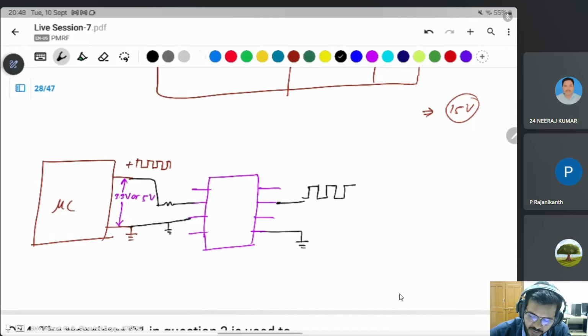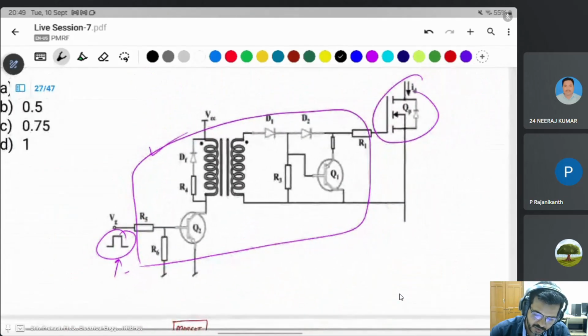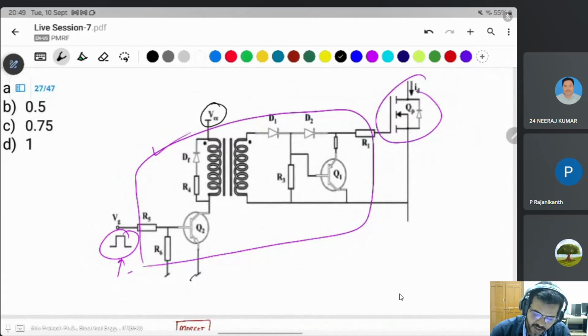Last, there is a requirement of a voltage supply. Whatever voltage supply you give to the driver is the same voltage given to the gate signal output of the pulses. This is the VCC. VCC is in your hand. It is how much voltage you want to supply to the gate voltage of the MOSFET.